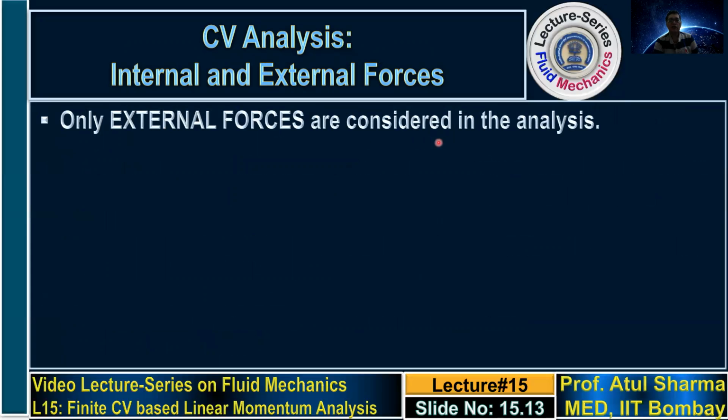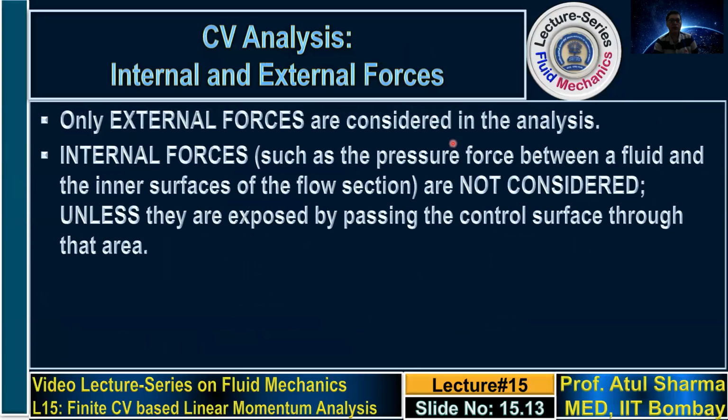Only external forces are considered in the analysis. Internal forces, such as pressure forces between the fluid and the inner surface of the flow section or the viscous forces, are not considered unless they are exposed by passing the control surface through that area.